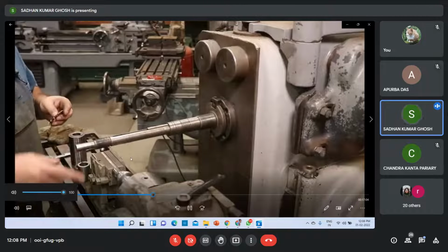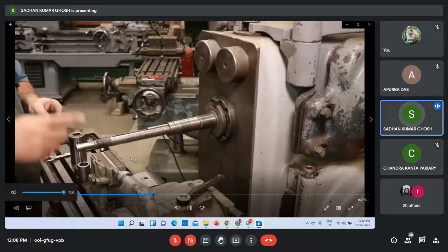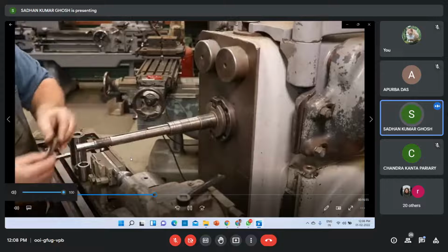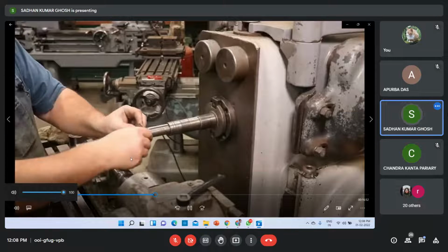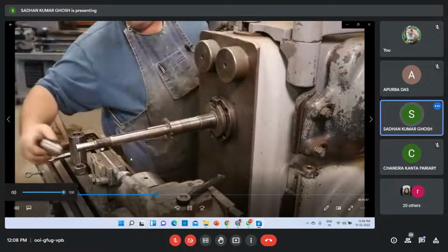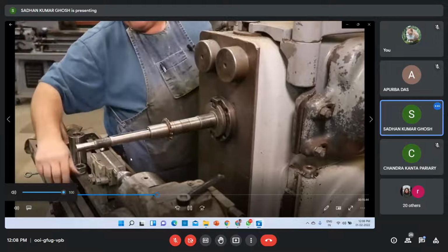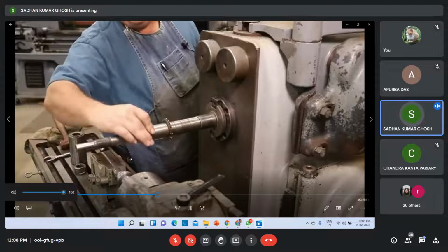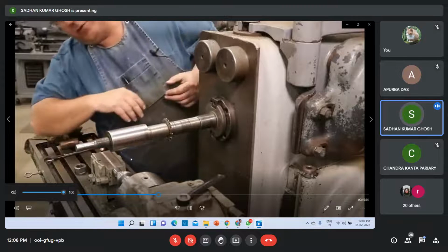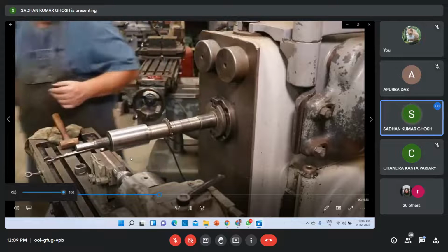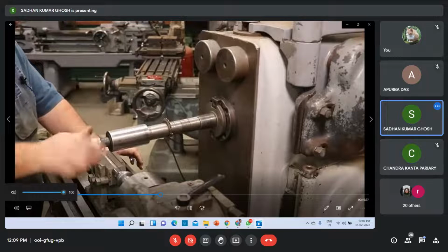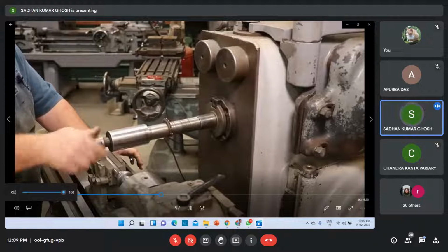I want to be turning in a counterclockwise direction so that my cutter is cutting into this down here. So got my cutter properly positioned, get it up on the key here. Alright, now I take my bushings, or my spacers rather, put them back on here. This is my bushing that will go right up in the overarm support. And we'll go ahead and screw this on here.